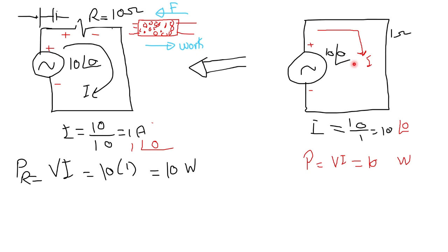Theoretically, the current should be infinity because the wire resistance is 0, but we'll assume again for simplicity that the wire's resistance is 1 ohm, so that the current in this circuit is 10 amperes, 10 and angle 0, the same phase as the voltage.